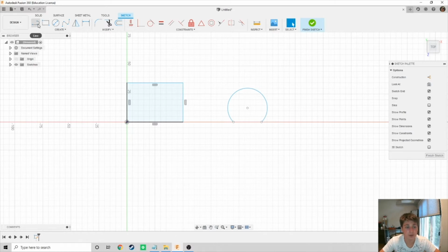However, when you're using the line tool, we have an exception to the 2-3 click rule that I had mentioned previously. I'm going to go ahead and start my first click, my starting click, and I'm going to draw out my line to, let's say, 36 millimeters. I'm going to do my second click, finishing my line. What you're going to notice is that after I've done my second click, I haven't clicked to start my line again. But because Fusion encourages you to make a closed shape, it's going to allow you to continue drawing instead of having to re-click.